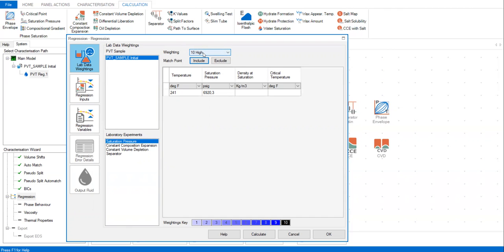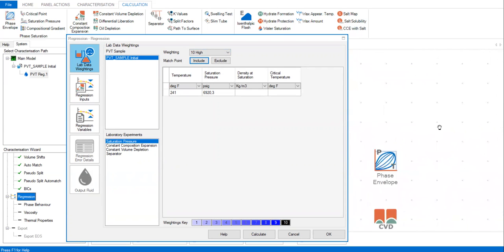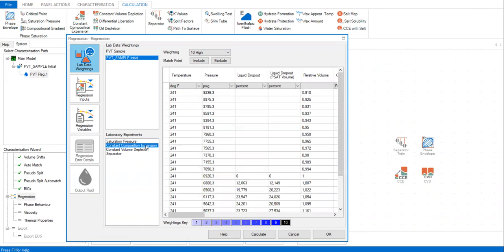And then it should be noted that obtaining accurate measurement at the dew point, especially for near critical fluid, is difficult, as the liquid and vapor phase become hard to differentiate. To avoid these uncertainties, you may wish to instead regress on the fluid density near rather than exactly at saturation pressure, if available. Okay, and then we continue with the constant composition expansion. All right.